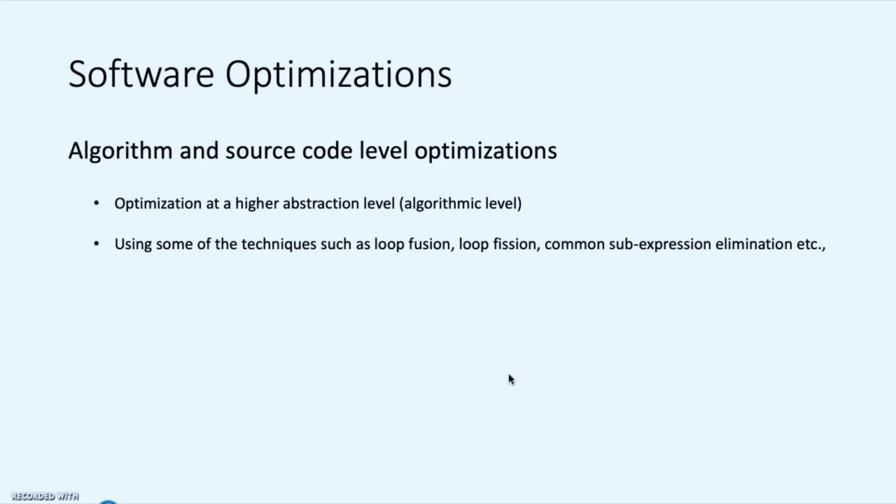So all these techniques are in a way helpful when you want to optimize the code and even the memory too. But there are some optimization techniques which increase the code size, like loop unrolling. So you unroll the loops so that you increase the code, but they run quite efficiently and consume less power. But the price paid is in terms of the larger code size.